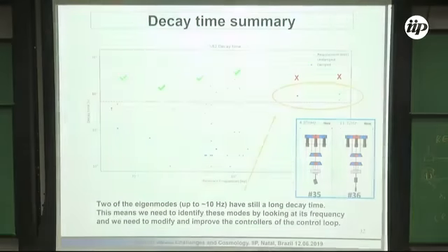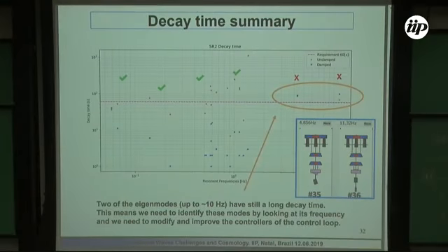Damping actuators, for sure, are always not perfect. They aren't perfect, but digitally you can perfectly balance them, while in this case you cannot correct. For example, we measure one suspension and we try to follow the same for the others, and I'm measuring at least that the decay time was below the requirement.